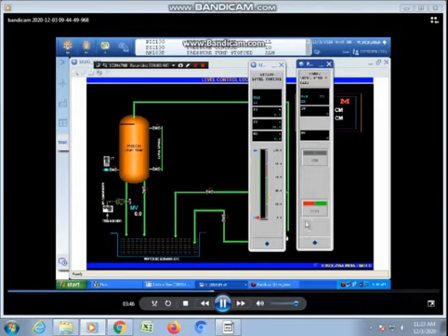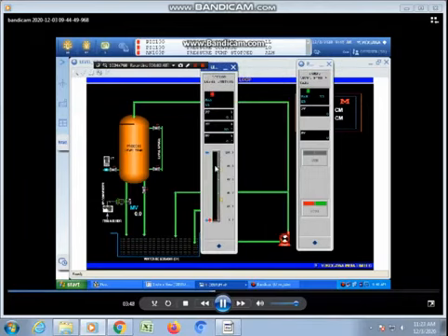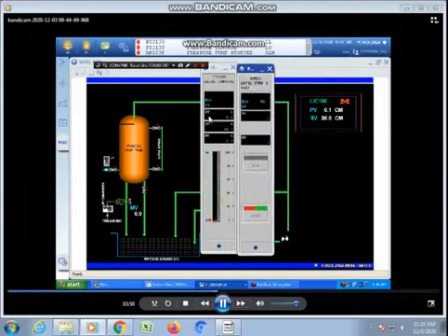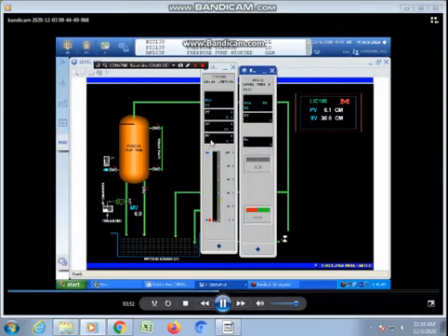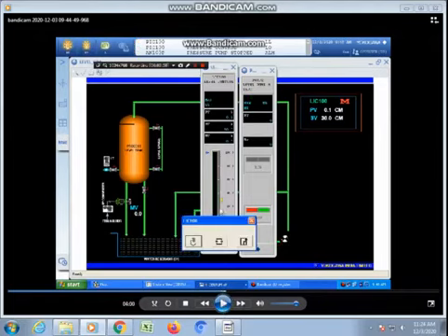This is to switch on off the pump. This is for the process diagram. Here we have process variable, manipulated variable, set point variable, and we can give the input. There is one thing you can see here, MAN, which means this is manual mode. When I double click this manual mode, we will get three things: manual mode, auto mode, and cascade mode. Three kinds of modes of operation we can do with this type of PID.